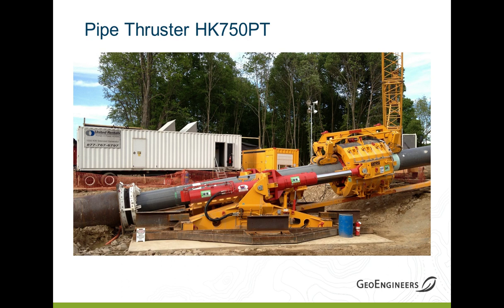This is a 750 metric ton pipe thruster on a project we worked on in central Pennsylvania. And you can see in this case, we're launching through an oversized launch casing. So the yellow building in the background is the control cab. And then right at the edge of the launch casing is the launch seal, the white apparatus with the black rubber gasket. And so that's another piece of critical equipment.